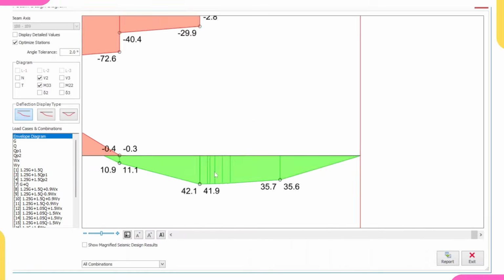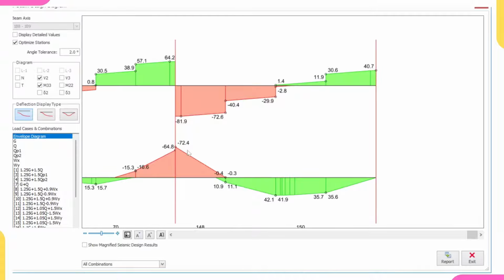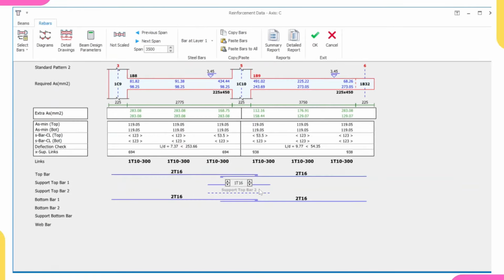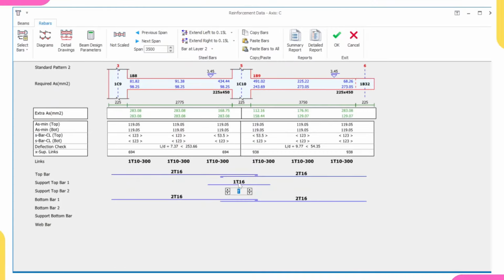So come over to this point. Because of this high moment, that's why we are having 3Y16. If you keep on increasing this reinforcement till it passes, then it can fail in shear. Look at it, it can fail in shear. Failure in shear means a sudden failure, just like sliding. So it can also fail in shear.